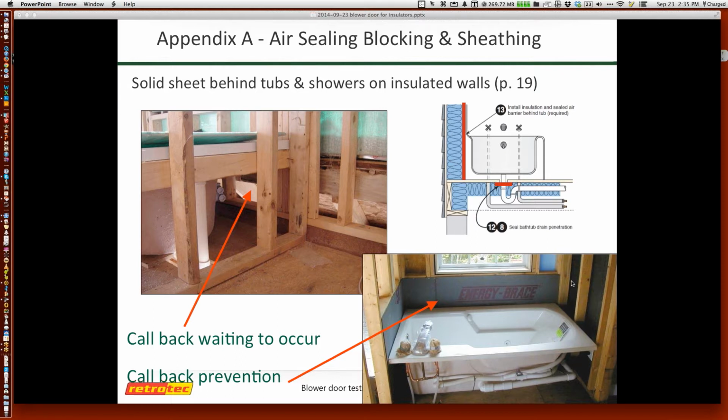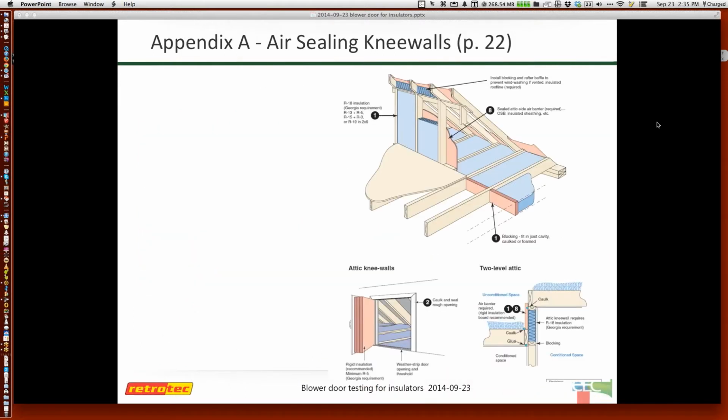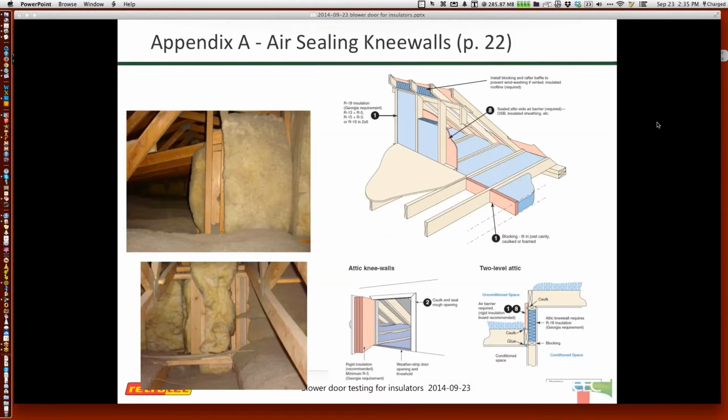It's not good, as you know, to have a void on the back, but some people just would come in later and just shove insulation in here without actually having the air barrier in place. So most people leave a couple of either fiberglass batts and some rigid board early in the game, or make sure the contractor is aware of that. Most plumbers aren't really taking care of that. So again, these are some other illustrations now.